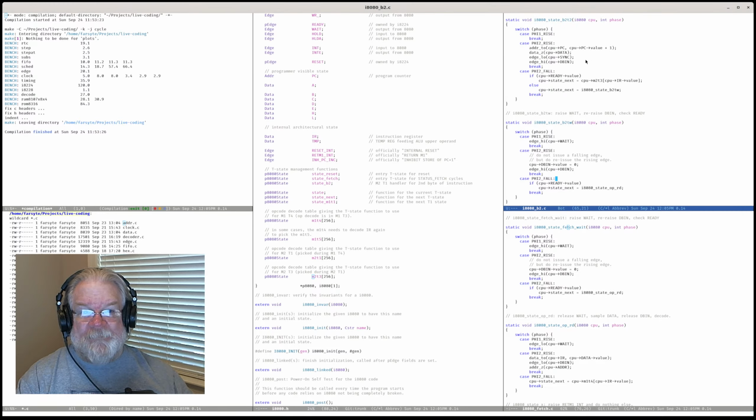Now, I'm not sure I can test B2 in isolation, because if I just add B2 to the system, nobody has registered themselves in M2T3. So literally, we'd hit the M2T3 and we would stall there. We specifically set that up so that any of these T states we haven't defined yet simply lock up the CPU and hold us in that state.